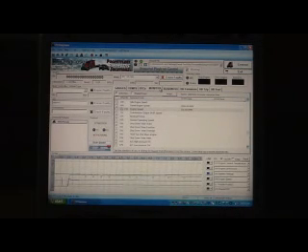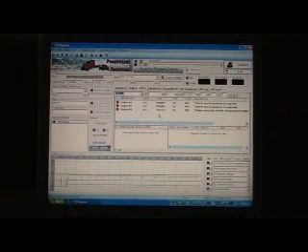For the most part, the monitor tab and the DTC tabs are the two tabs that you will be using the most. In the DTC tab, you can erase the fault codes by selecting the Erase Fault Codes button that is illuminated for the particular module that has faults. In this case, it's the engine. 3 fault codes related to the engine. To erase these codes, you would click on this box.